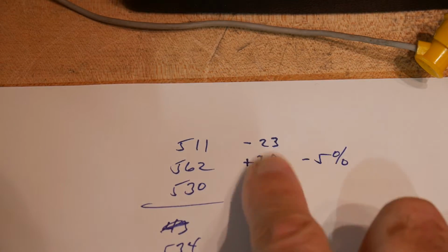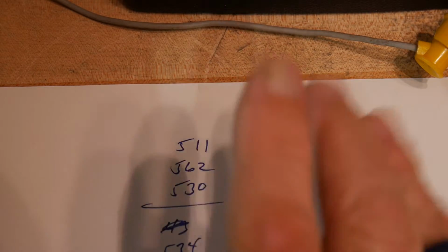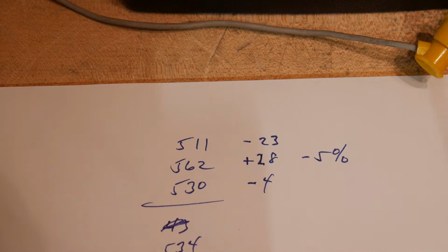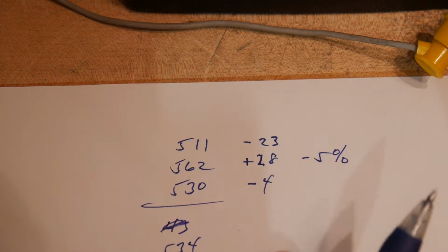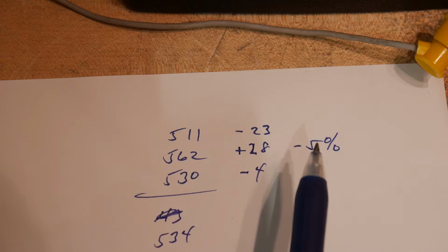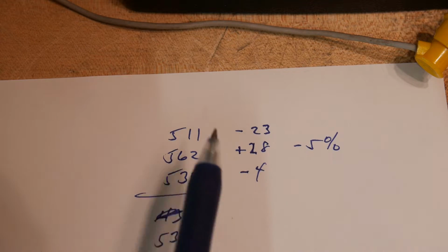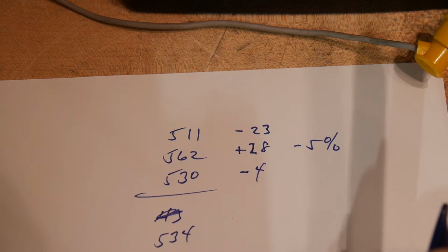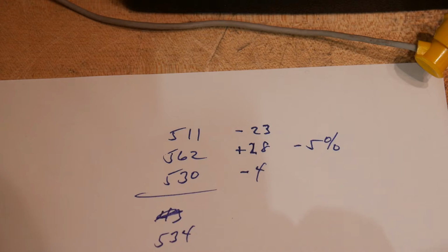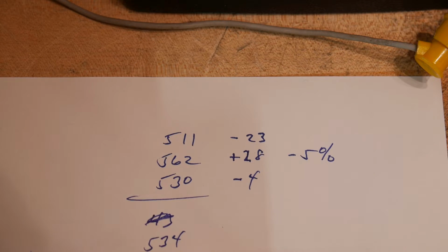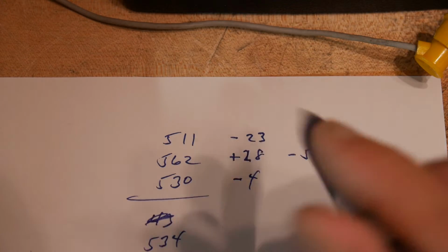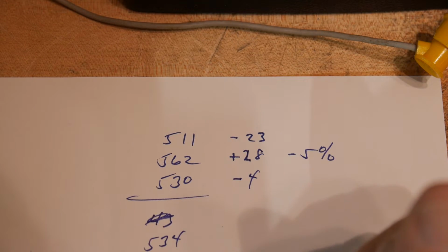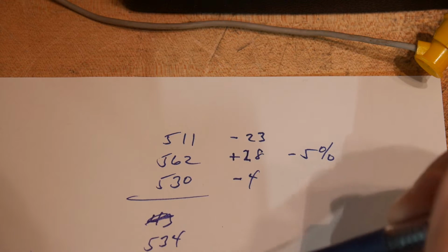Okay, so we're current mirroring to about an absolute error of 5%. Some better, some worse. So yeah, not too bad. It doesn't use many transistors. Again, it would be much better if the transistors were matched. And it also is the simplest type of current mirror.